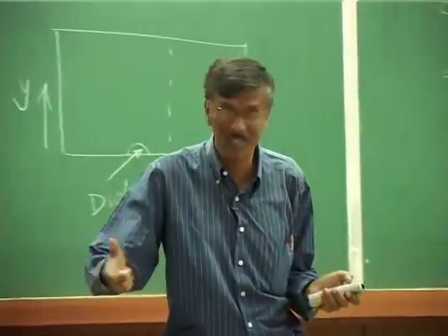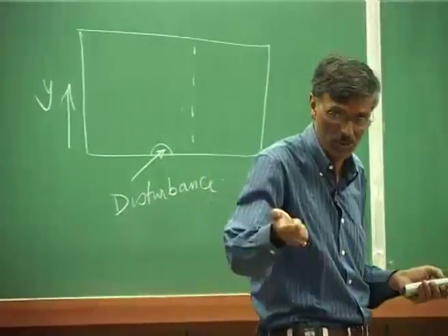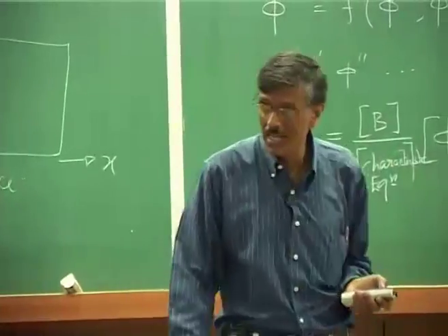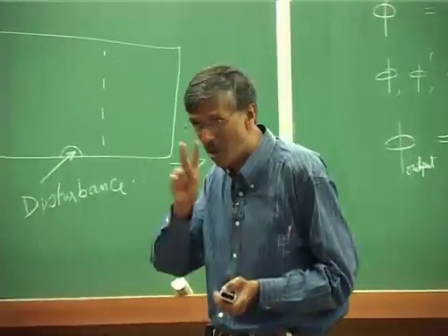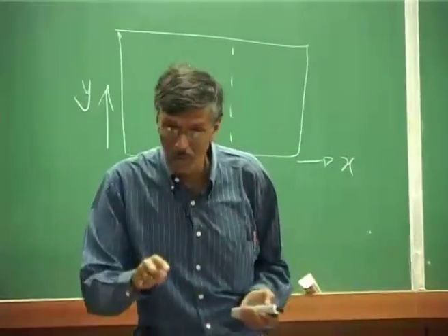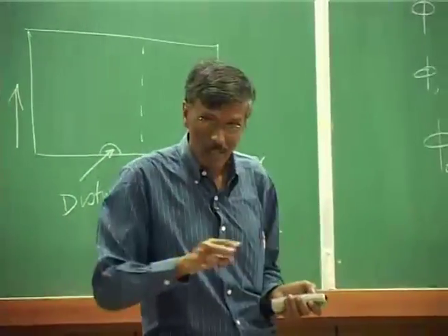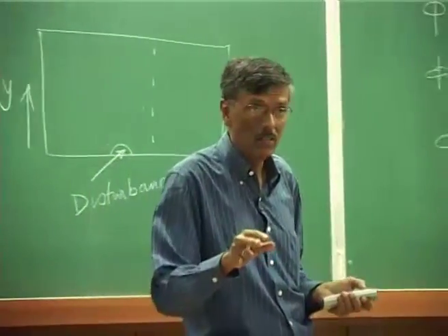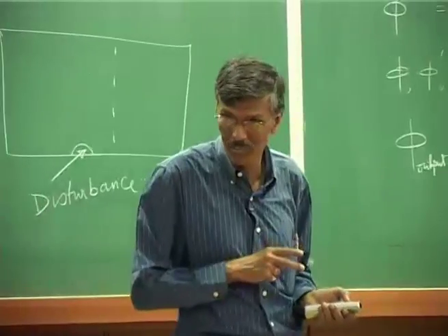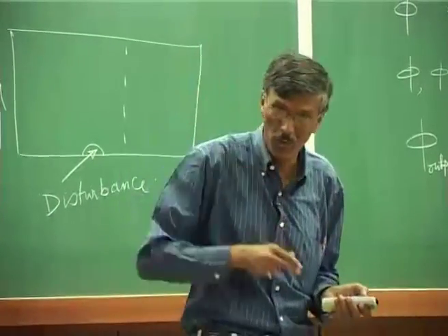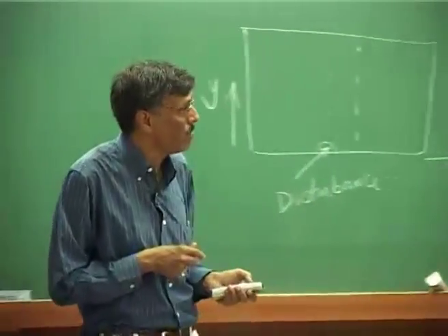So, this is the problem of parasitic error growth we talked about in the last class: 2 of them are admissible and 2 of them are non admissible, and if you do not pay attention and care, the numerical error could ride on those non physical solutions, and that could explode and give you a totally meaningless result.